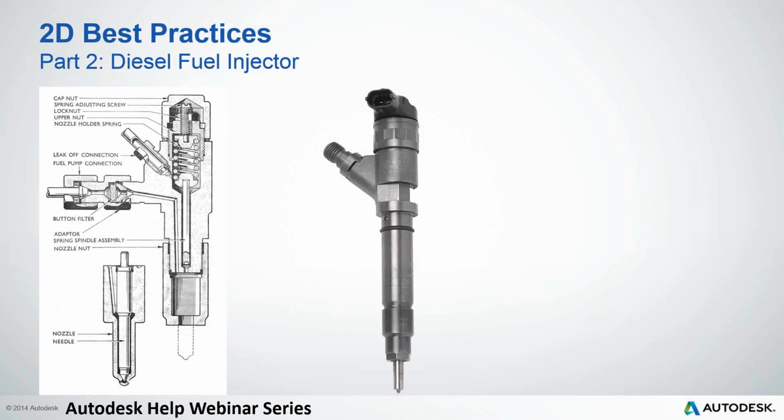I've noticed a lot of folks lately having a hard time getting enough elements through cross sections or ports in flow areas. A while ago, I helped some people try to model nozzles and other things like that. In order to capture flow, you have to have a bare minimum of 3 elements through the thickness of your flow section, and that can just drive your element count to be unrealistic. So I thought this would be a great application to show.